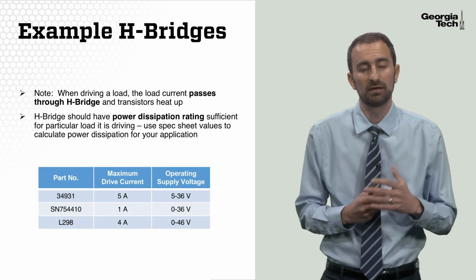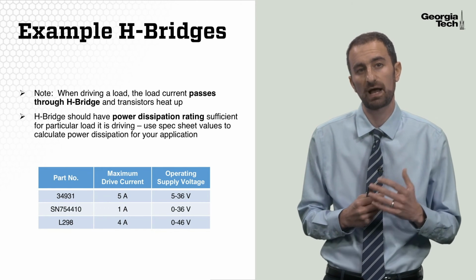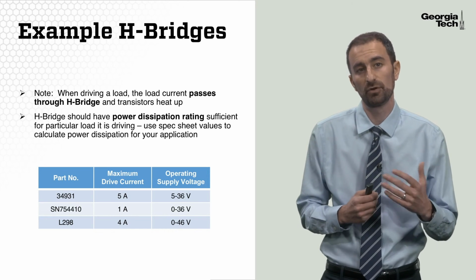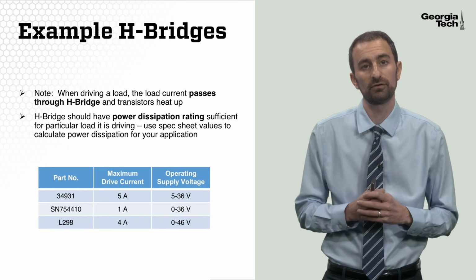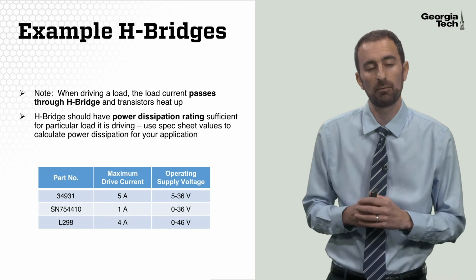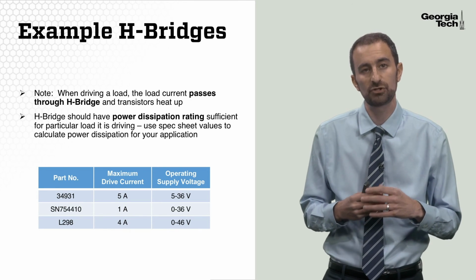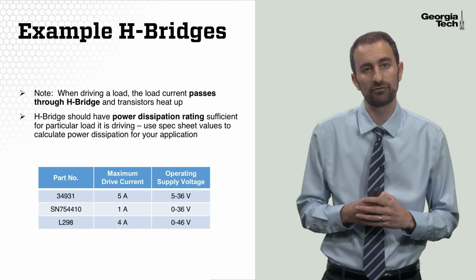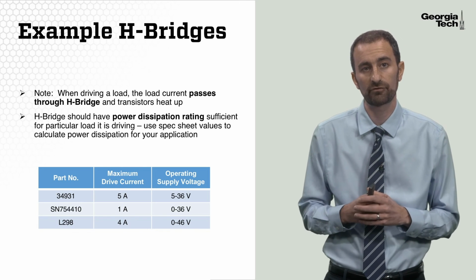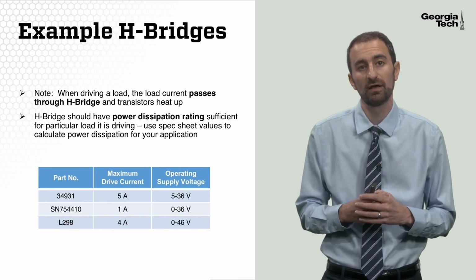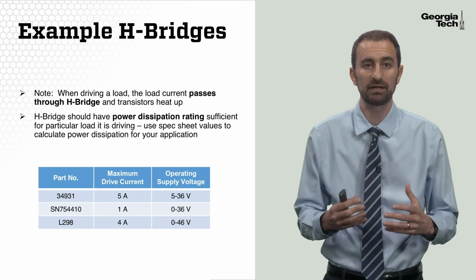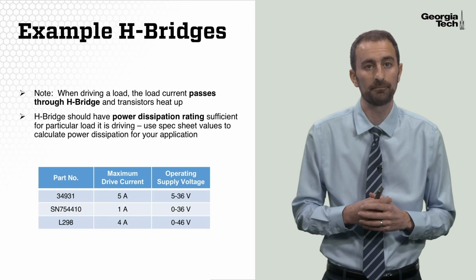planning to run. Now, many spec sheets will give you an equation for how to calculate power dissipation for your H-bridge depending on the load you're using and the voltage that you're supplying to your load. And you can use that power dissipation equation to compute how much power is going to be dissipated, and then check that that H-bridge integrated circuit is sufficient for your application. But you should understand that these motor driver circuits and the H-bridge are going to heat up when you operate them, and you might need to put a heat sink on them in order to keep them cool enough and make sure they don't burn out.